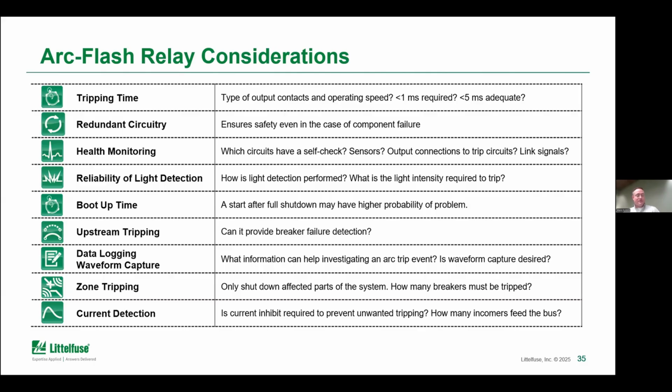Another item here is the boot up time. So this is something that maybe not everybody thinks about, but once you are doing maintenance on a system, and so it might be totally shut down, when you come back online, that's maybe one of the times where there could be issues. Maybe somebody forgot the earthing straps on the phases, or of course, the classic example is somebody left a wrench or some piece of metal laying around or touching some of the phases.